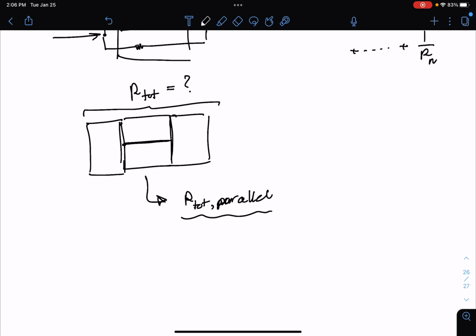Can we safely assume that heat transfer here is one-dimensional? Because the idea was one-dimensional heat transfer needs to have uniform temperature on all sides, right? Here, we have different walls. We can't really assume that we have uniform temperature here and here. So what should we do?